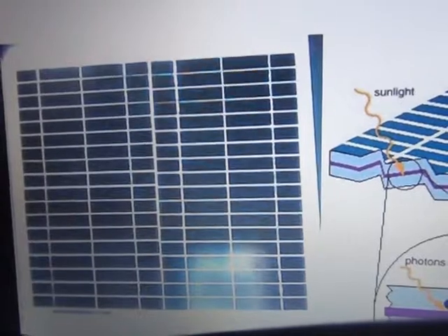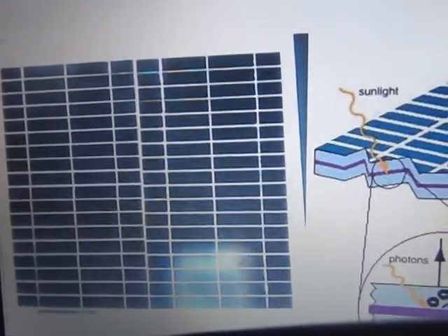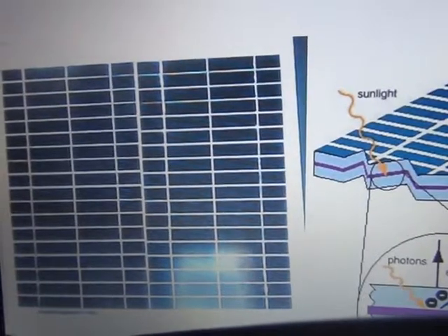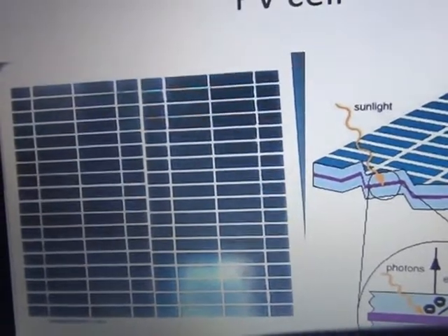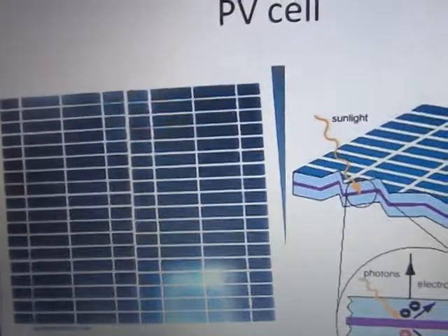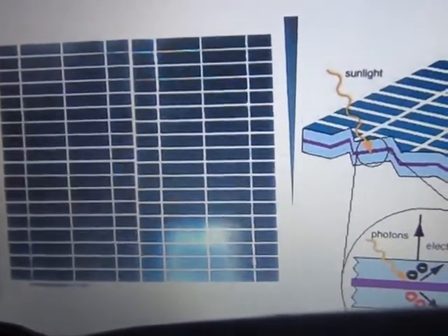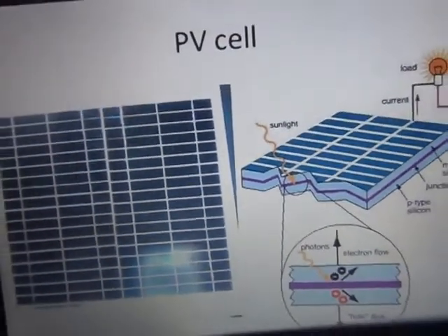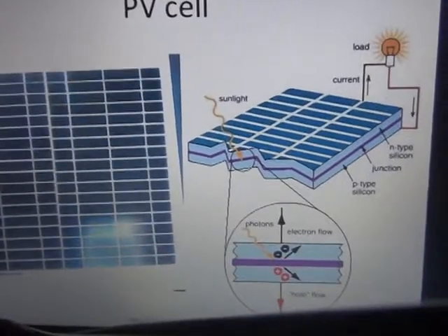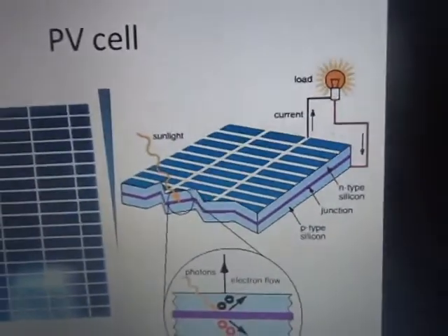If it was a single plate which generates a voltage above the battery voltage, I could have just connected it to the battery for charging whenever that voltage crosses the battery voltage. But there is a problem with this, called the overcharging problem. So once your voltage is higher than the required charging level, you should give it a PWM control. PWM is just switching on and off the supply being connected to the battery, and the battery will act as a load in this MPPT technique.